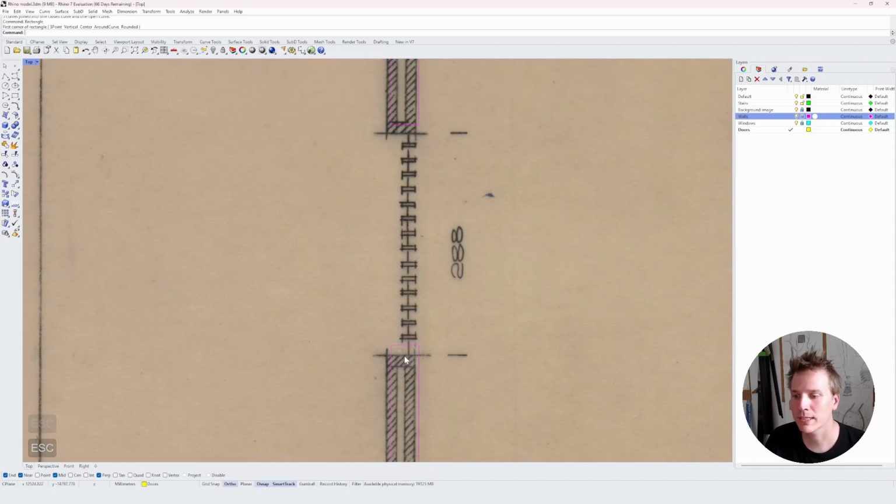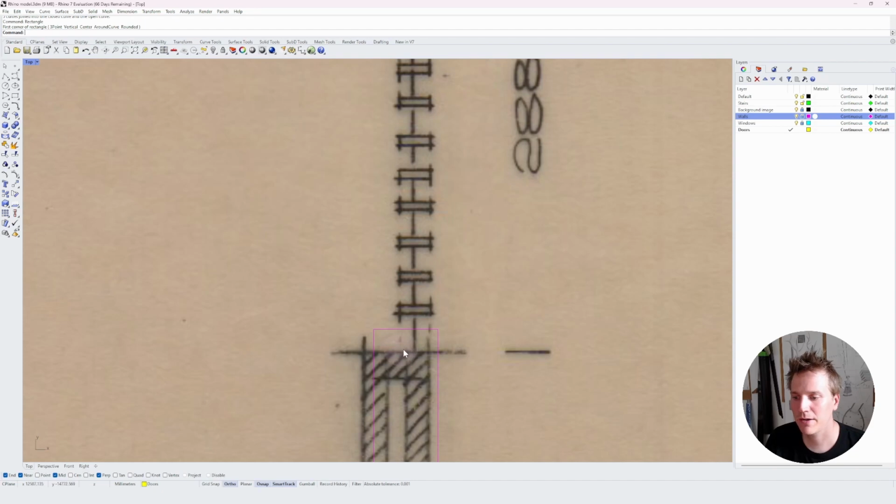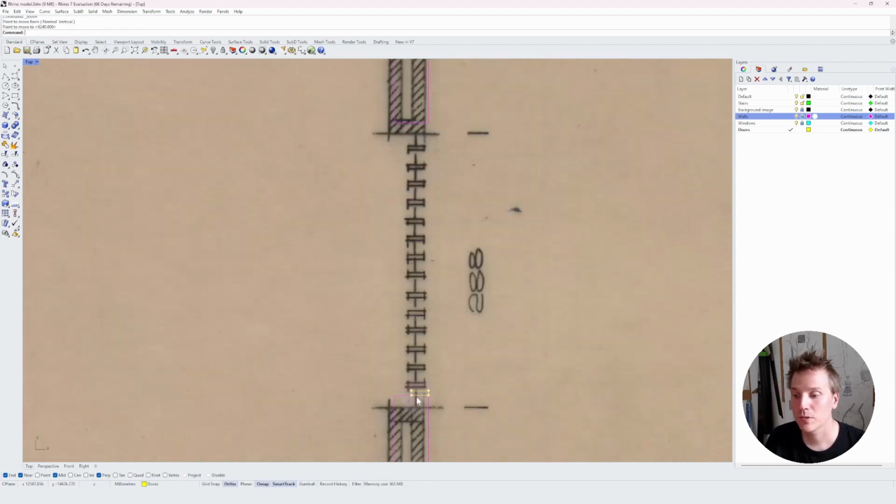First I'm going to make one rectangle, and I'm going to assume that it's kind of half the width of the wall. So rectangle from here and then to the middle of the wall, and then let's just say that it's 5 centimeters or 50 millimeters. Select that, move it in here, and now I'll use the array command, so array, and in the X direction, which is the horizontal direction, I want just 1 now, but in the Y, which is up and down, I want 15, and in the Z direction, again 1.